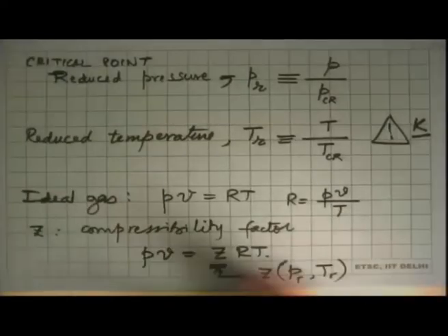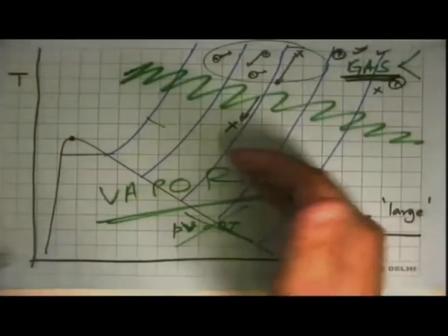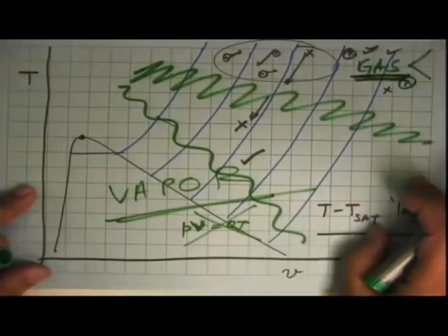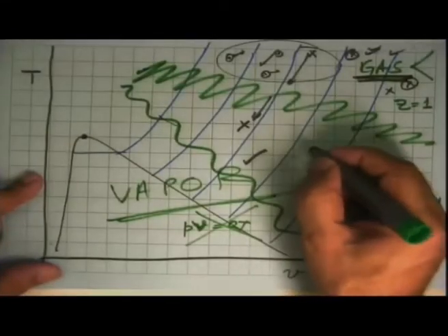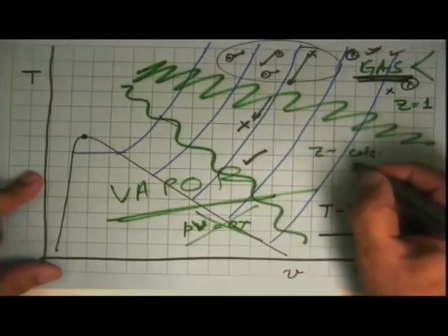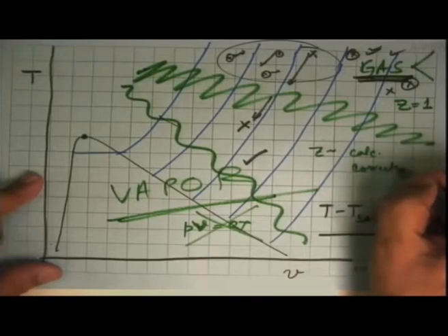And once we do that, we get a little better in using a very simple equation of state a little further down. So we can say that, look, now I don't have to stop here with PV equal to RT. If I start using PV equal to ZRT, maybe I can cover this more region also. In this region, Z is one, ideal gas behavior. In this case, Z is somewhat off, but I can calculate it and make a correction. And you can continue that logic here also.